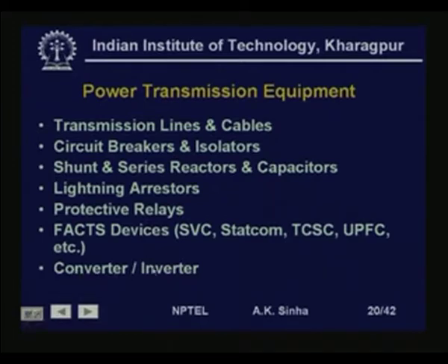For HVDC transmission system, we need converters and inverters at the two sides. In fact, these basically use gate firing devices, that is controlled rectifier and inverter devices.